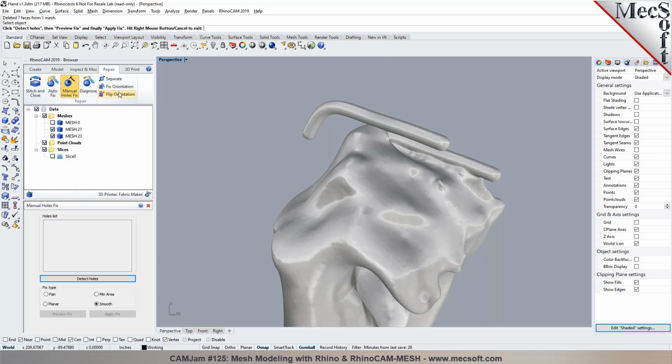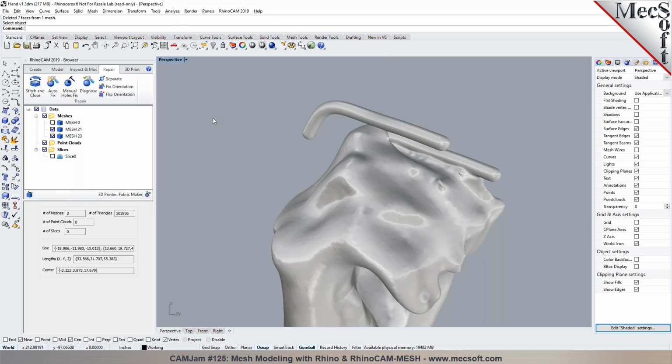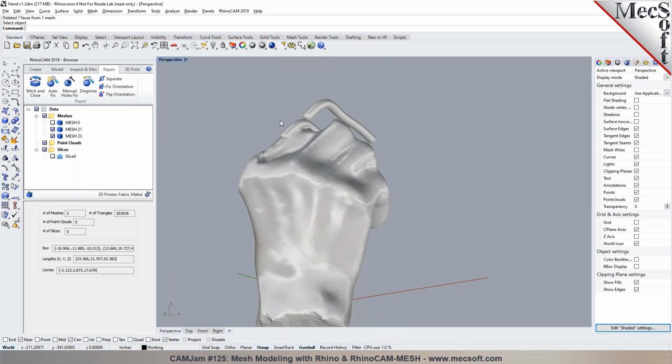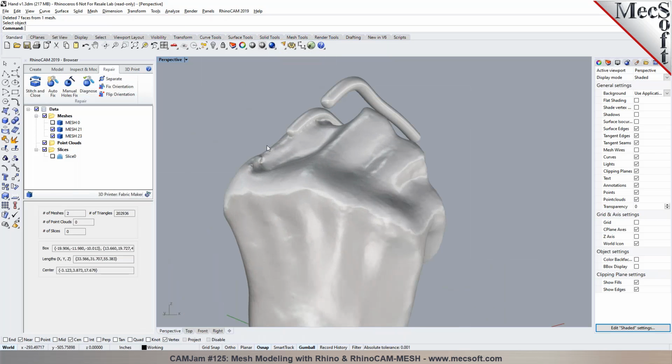But individually, if you want to do it, you can use these tools. So if for some reason you want to drill in and do it in a certain area, you could delineate that by using these other tools. Absolutely. Okay, and then the flip orientation would flip the entire thing. Yeah, flip orientation will reverse the orientation of all the triangles in a mesh. So if they're all pointing towards the inside, and you want to point them towards the outside, it'll just flip the orientation.